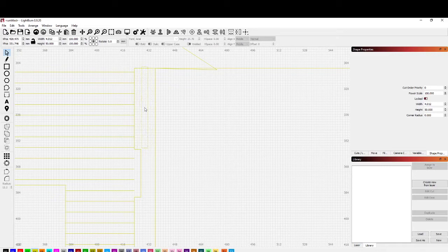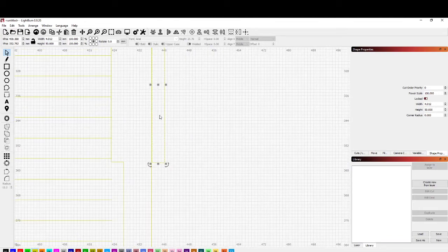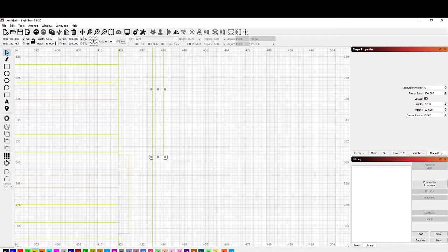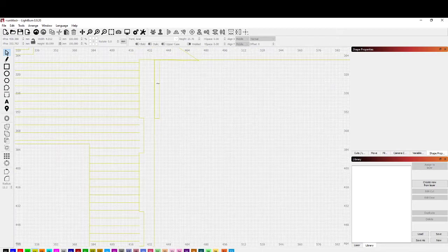You can see up the top there it's drawn this 50mm, but you want this to be a tiny bit bigger, because by the time you lose the curve from the beam, you lose a little bit. So instead of 50, I'm going to add whatever your curve is, like say 59. It's going to make the height of this a little bit bigger, so now it's going to be a bit tighter to fit in here, so it doesn't just easily fall out.